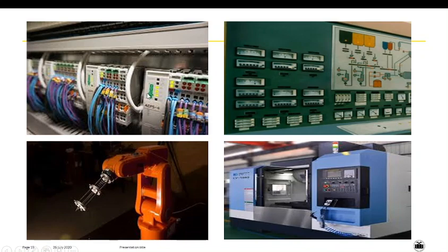So this is one kind of PLC. These wires you can see are coming from various sensors, and their output is given to this controller so that the controller will process the information. Again, such wires are connected at the output terminal, and this output is given to the actuators. Again, certain wires are connected with some supervisory level devices. So multiple controllers are connected over here.